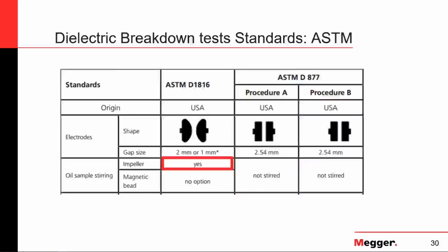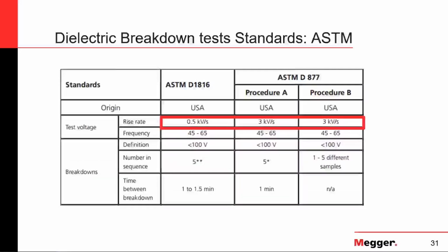So now let's look at the actual test vessel we need to perform the dielectric breakdown voltage test. It is recommended that the vessel material be one you can see through, so you can observe the breakdown.